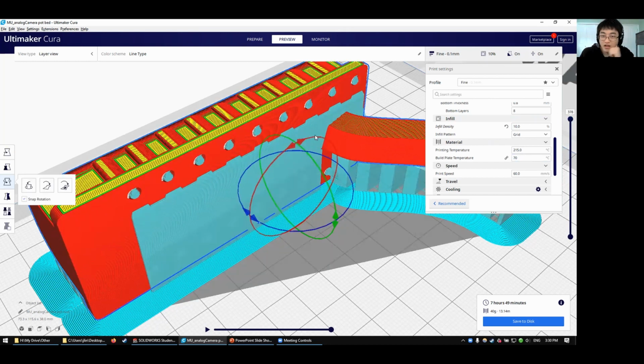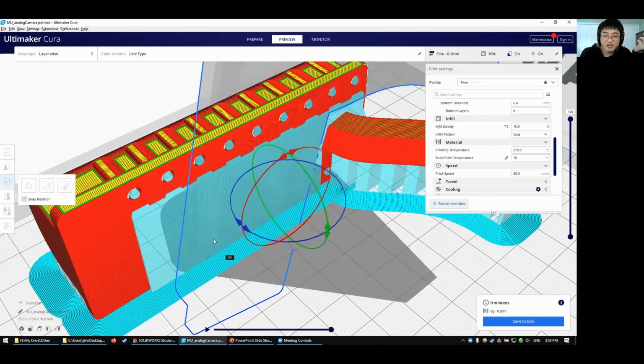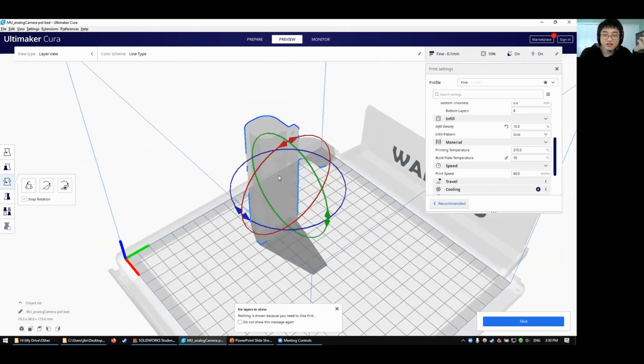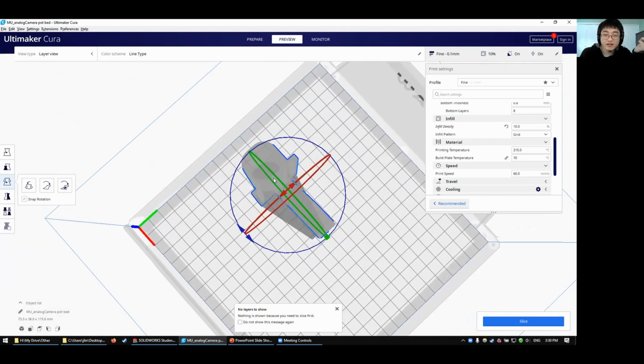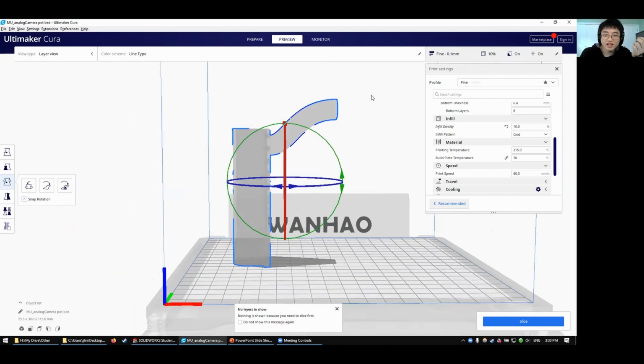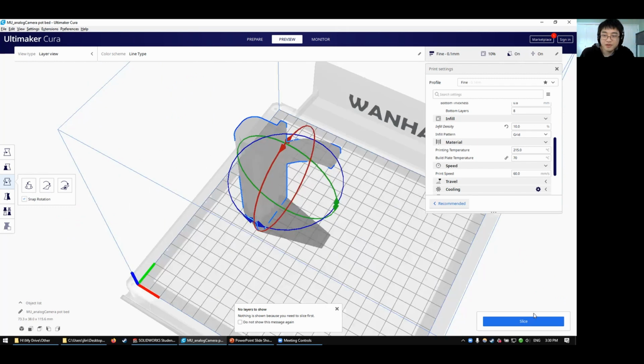To fix that, I'm going to go ahead and rotate it because I don't want this to take a lot of plastic just to print the supports. So I think that this way might cut down on the amount of supports needed because it'll just print straight up, except for the long weird path coming out the side. That thing will take a lot more support, of course.